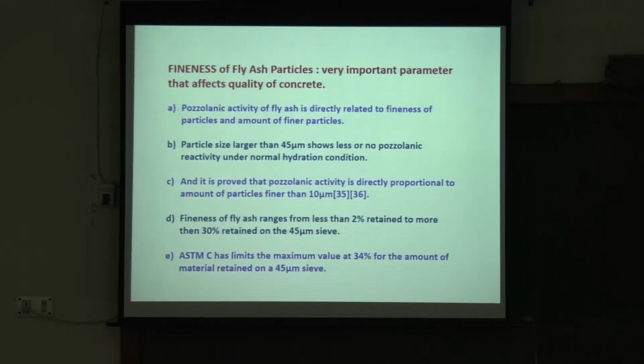Pozzolanic activity, that means absorbing the water, is really related to the fineness of the particle and the amount of the finer particles. That means how much you have. Particle size larger than 45 microns shows less or no pozzolanic activity. This is very important.